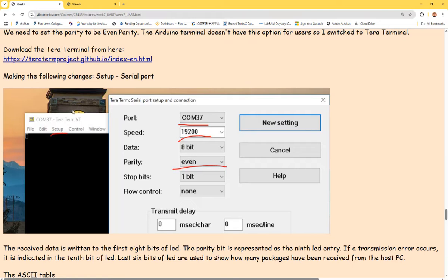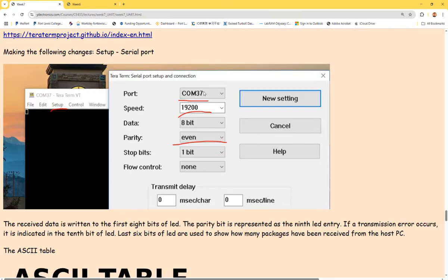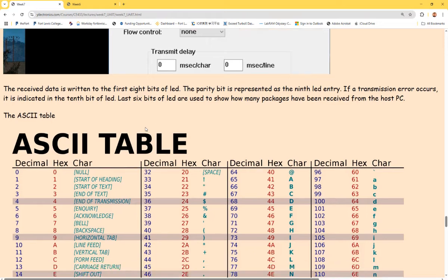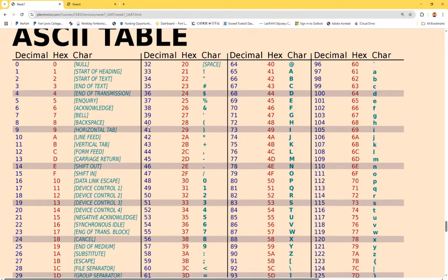These are just terminals you can open up in your Windows operating system, and you can change the port number. You can change the baud rate, which is something we'll talk about in a bit. You can change the parity bit, all these kinds of parameters. And keep in mind, there's a TX and RX module. It's a digital block designed by whoever designed your laptop or desktop. Right behind that USB port, there is an RX and TX module.